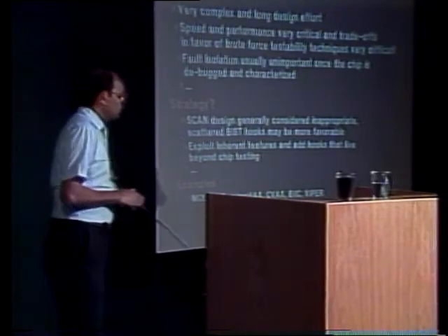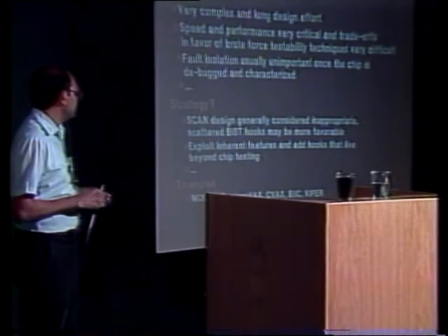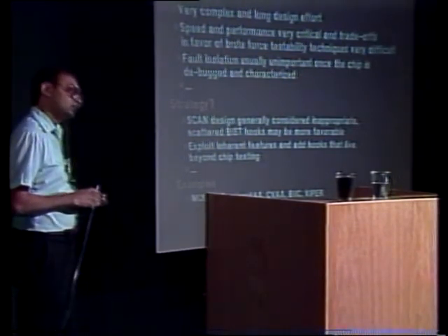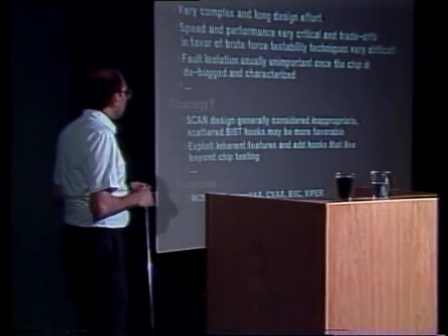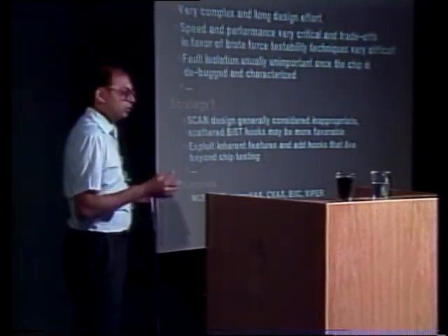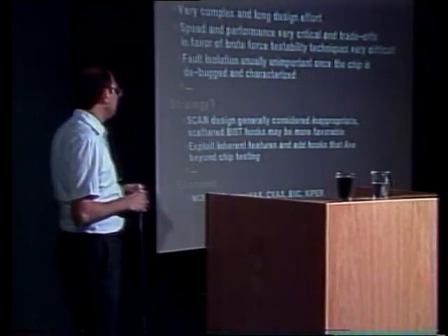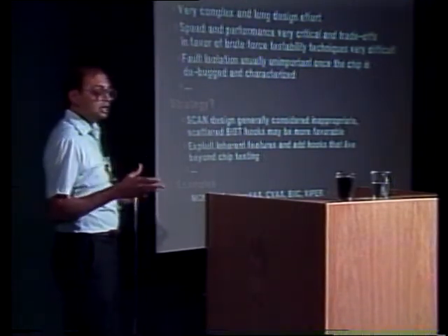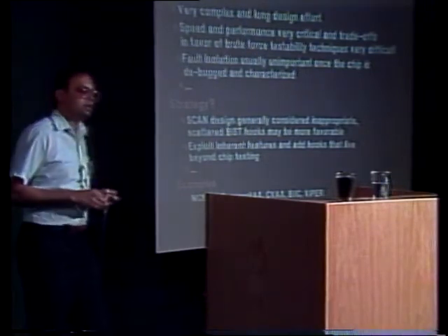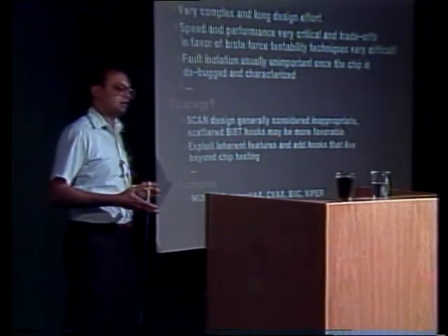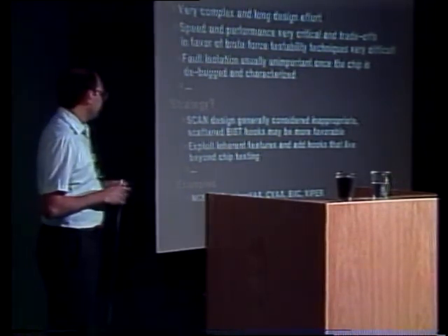Okay. So we don't think that scan design is very appropriate, but some scattered self-test hooks and even scan hooks may be appropriate. The strategy here should be to again exploit inherent features in the design for testability and add test hooks in such a way that not only do they help for chip testing, but they live beyond that and can be exploited for the system or the module test environment.